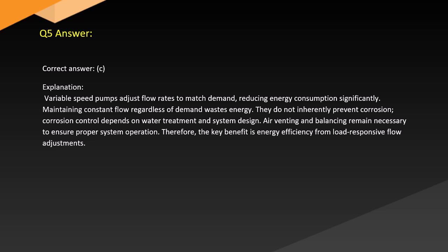They do not inherently prevent corrosion. Corrosion control depends on water treatment and system design. Air venting and balancing remain necessary to ensure proper system operation. Therefore, the key benefit is energy efficiency from load-responsive flow adjustments.